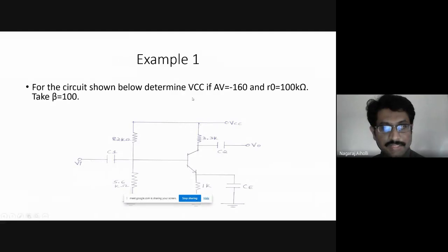Now here there is a junction, so we have VTH here. VTH is the voltage at the junction. Negative to positive is plus VTH. Then as we come to the other side, positive to the base, negative to the emitter, so positive to negative, minus VBE, then positive to negative minus IE RE, emitter current multiplied by emitter resistance, the emitter voltage. So the KVL equation: plus VTH, minus VBE, minus IE RE is equal to 0.